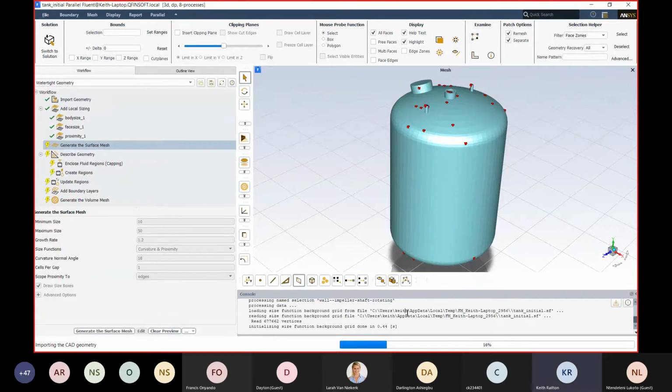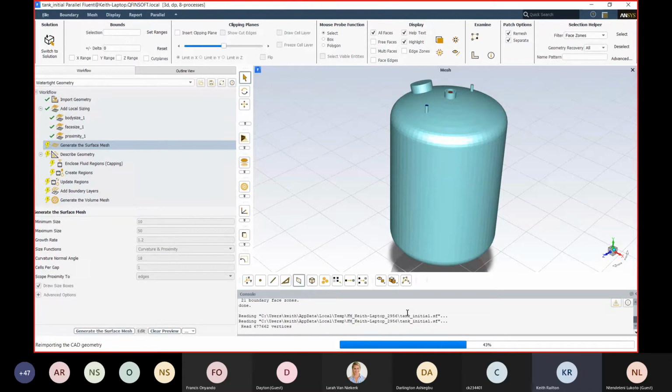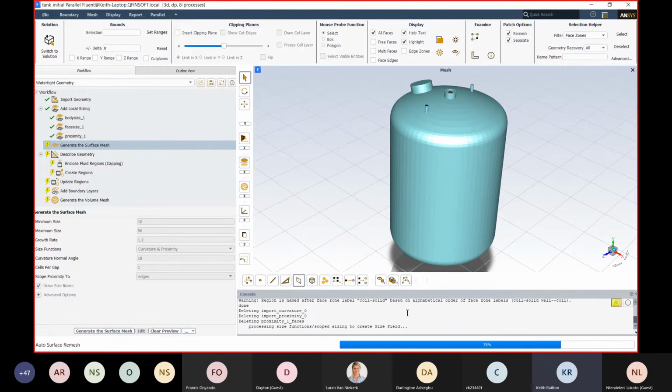Okay, so what makes Fluent Meshing better than other meshing software? I think they've worked a lot on the meshing technology, and they now have fully polyhedral cells, which are very robust cells. Then they also have what they call polyhex core, where your surface mesh is polys and your internal mesh is a hex core kind of mesh, a Cartesian type of mesh. With that technology, Fluent Meshing has become very strong at what it can do.